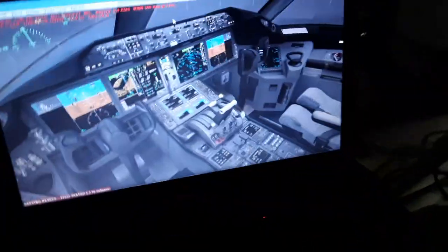So we're going to be flying the aircraft like this, with the flight controls. So I will talk to you about the flight controls now. How you use the yoke to control the horizontal tail of the aircraft for climb and descent. Also the ailerons, the spoilers and the flaps. Use the control wheel to make left and right turns, bank rolls in flight.